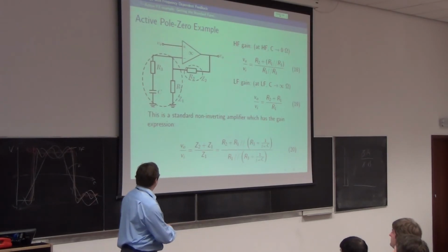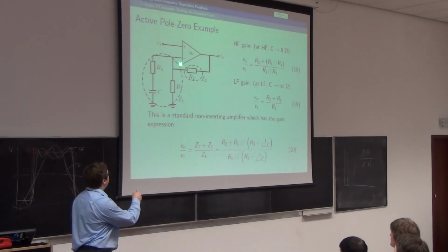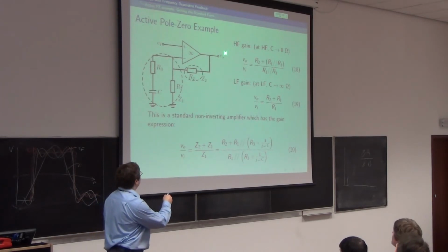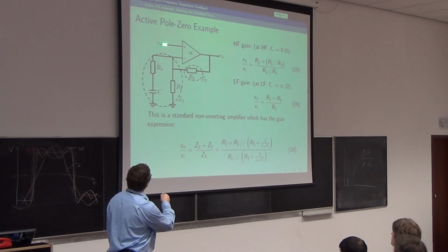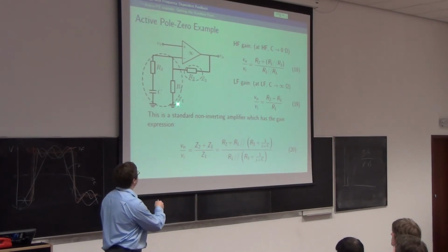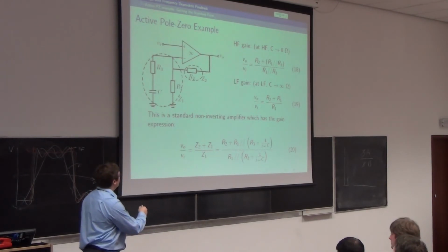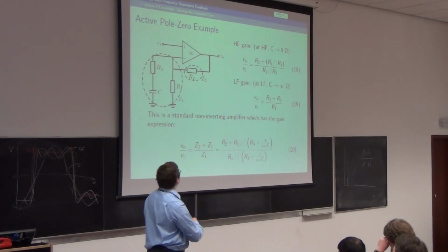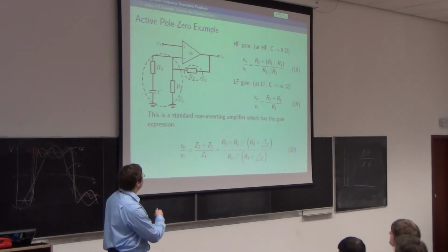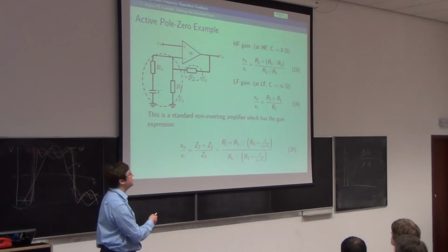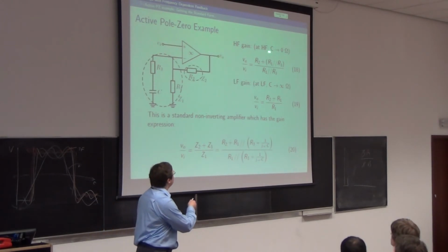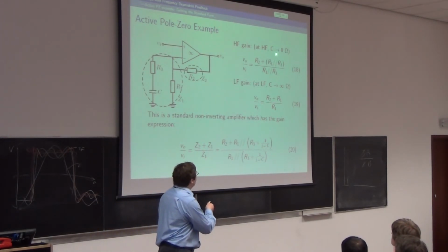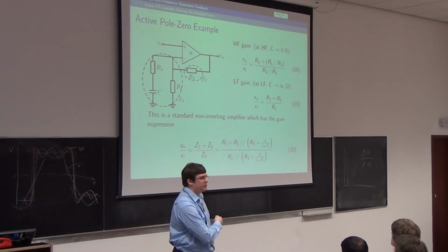And we would usually say, well, V minus is VL in the potential division of R2 and this lot. So I call it Z2 and Z1. And we can do the same thing with the high frequency and low frequency gain that we usually do and say at HF, which is F tends to infinity, the impedance, sorry, that's strictly wrong because I've got capacitance in ohms, which is a total lie.